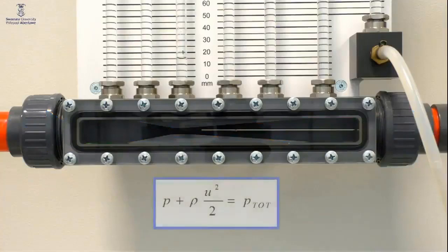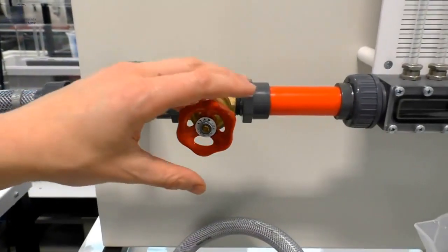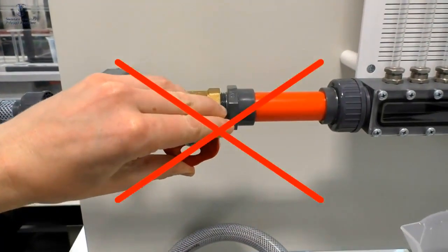So to verify Bernoulli's principle, you will need to measure the fluid velocity and the static pressure throughout the tube. When you arrive at the lab, the equipment will already be set up by the demonstrators, so do not turn the valves or this will affect your results and you may need to repeat the experiment.